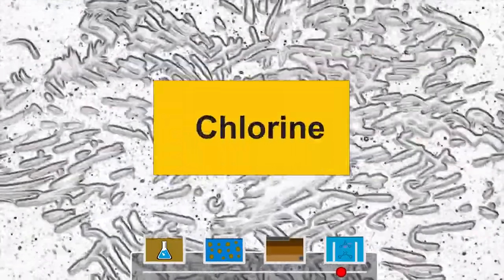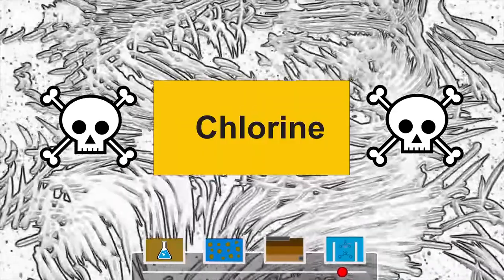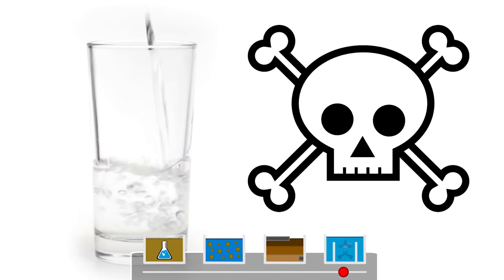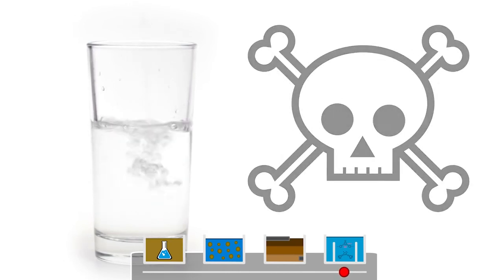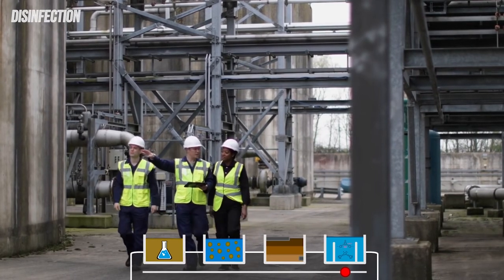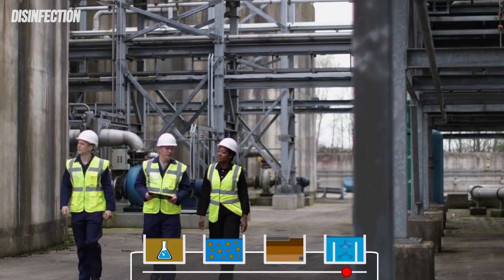Even with all of this, chlorine is used mainly because of how it kills pathogens. It not only kills any pathogens in the water at the plant, but residual chlorine levels also remain in the tap water, killing any contaminants that might get introduced after leaving the plant. Most cities or states will have maximum or minimum chlorine levels in the treated water in order to keep both the water treated and city residents safe.